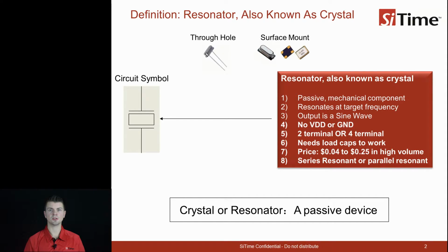Crystal resonators are usually offered in standard packages by multiple vendors. There are 2 and 4 terminal devices. The package's nomenclature consists of the package dimensions in millimeters with the longest dimension listed first. Each dimension is listed as 2 digits to accommodate decimal values. For example, 3225 means a crystal package which is 3.2 millimeters long by 2.5 millimeters wide. Common crystal resonator footprints are 3225, 2520, 2016, and 1612.